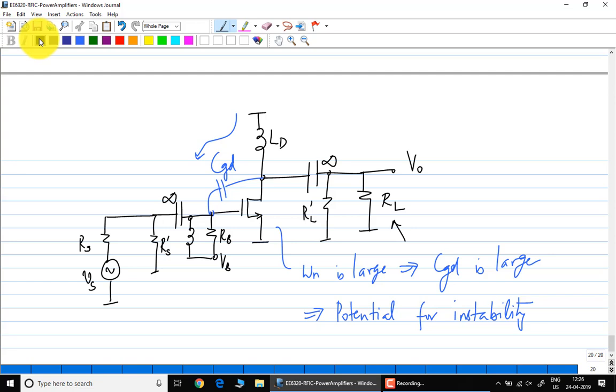Cascode. Remember right from the beginning, the cascode helps you get unilateral behavior. In the case of the LNA, the stability would still have been a concern. We did not have a strong swing limit, so we went ahead and added it anyways. The advantage of the cascode is that whatever you do at the output does not affect you at the input. The common gate transistor is like an ideal current controlled current source. It has an infinite output impedance, very low input impedance.